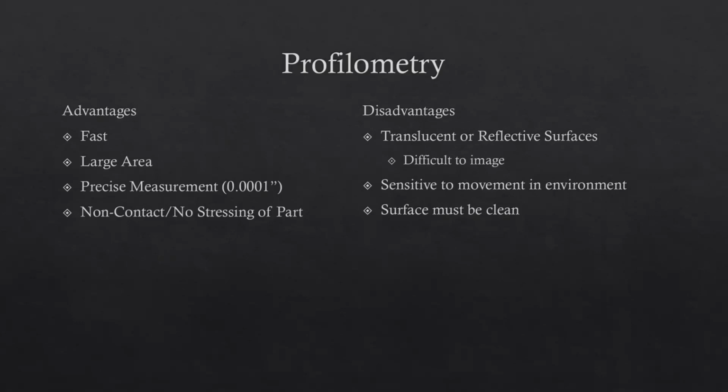And what that allowed us to do is take a profilometer, and where we started to use these a lot, where it was very critical, was for hail damage. Because when we'd have an airplane fly through hail, the surface, the top and leading edge of the wings, the nose, the area above the windshield, and the top of the fuselage would look like a golf ball.